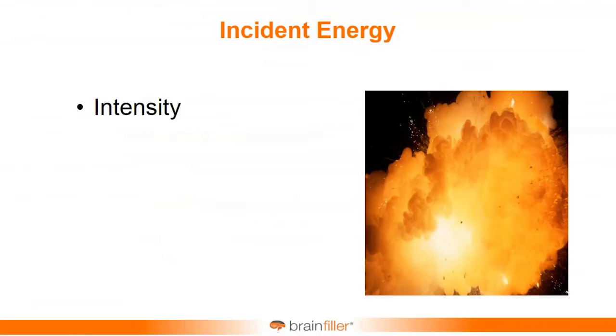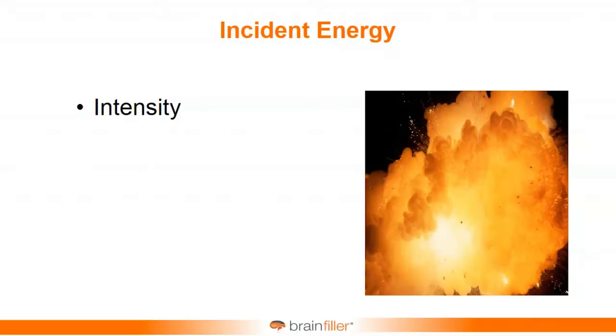And for this, the incident energy, it's a function of many different things. As I said, typically this is going to be based on a calculation using the IEEE 1584 equations. And those equations require a lot of different information. And one term that I use is intensity. I don't know that anybody else uses this, but when I talk about intensity, what I'm really talking about is short circuit current. Short circuit current defines what we'll call the explosiveness of the arc flash, and it's also important in calculating the incident energy.